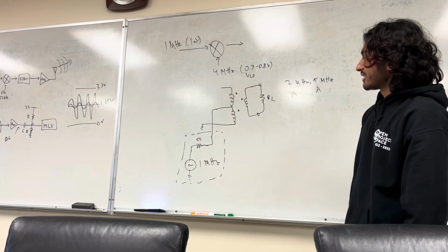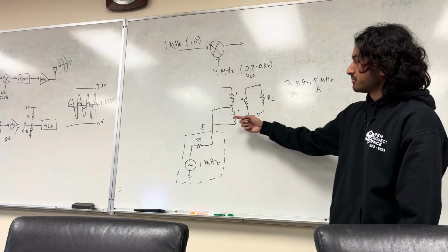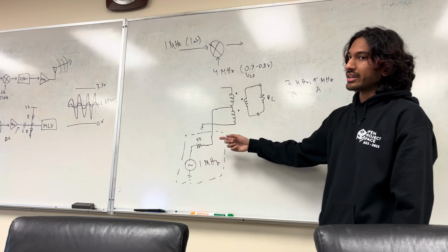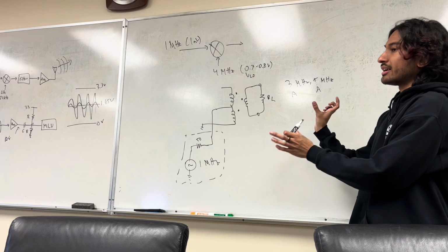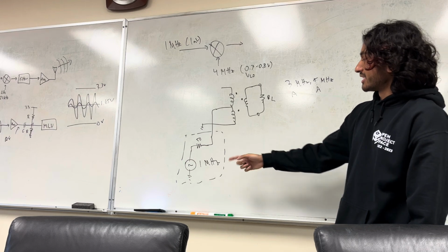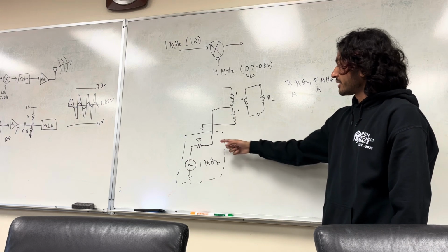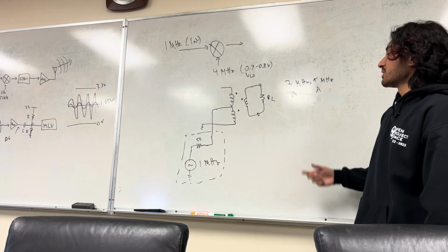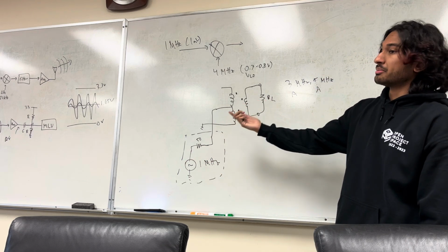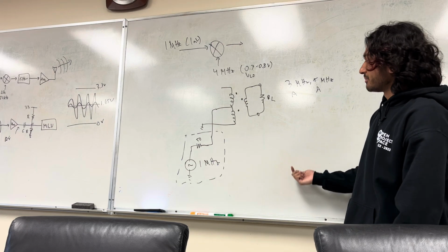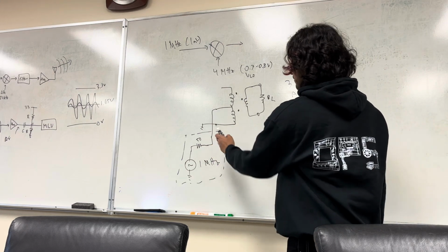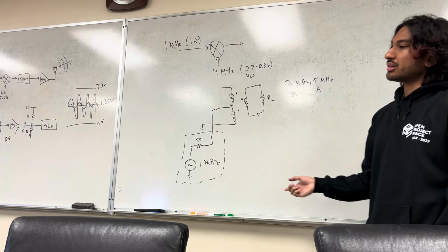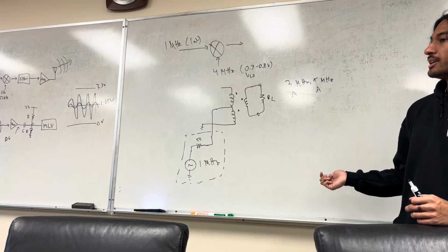And, well, why is that an issue? Well, if these components are too large, they can damage our MCU, right? We want to have our MCU be isolated, so we want to make sure that if there's any reflections or any leakage, that this is as isolated as possible from this. So what do we do? We put a buffer, right? That's kind of standard, makes some sense. So we're going to put a buffer here. That solves the isolation problem a bit more.